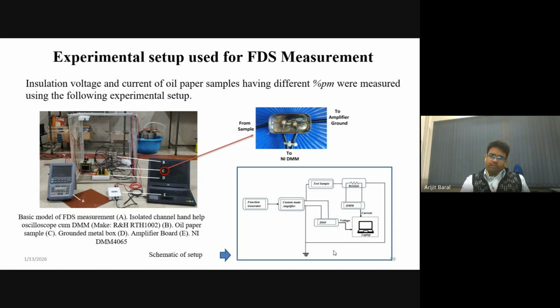Here I must elaborate a little bit more. If you are talking about a parallel plate capacitor or any dielectric material, it will basically behave like a capacitance. The capacitive reactance offered by this dielectric material to any AC voltage will be 1 by 2 pi fC. So if the frequency increases, this entire capacitive reactance decreases.